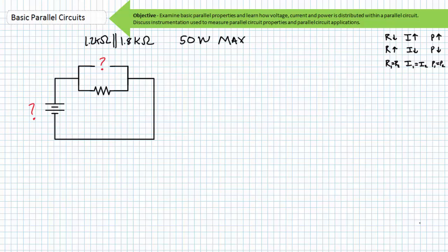My question to you is twofold. First, which resistor burned up and which resistor rode out the storm in, if not style, survivor mode? What is the 4-band color code beneath that fire blackened exterior? This is a trick question, by the way. A 50 watt wire wound resistor would not use the 4-band color code. It would be about the size of a big old fat highlighter marker and probably have the unknown resistance value and the words 50 watts clearly written on one side.